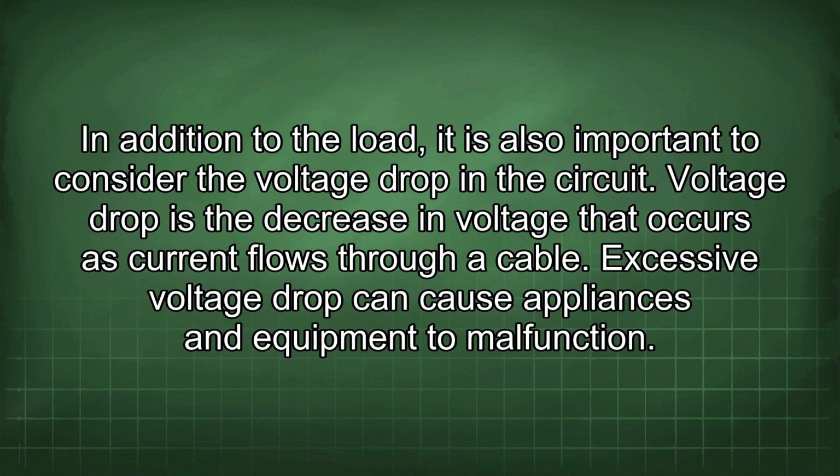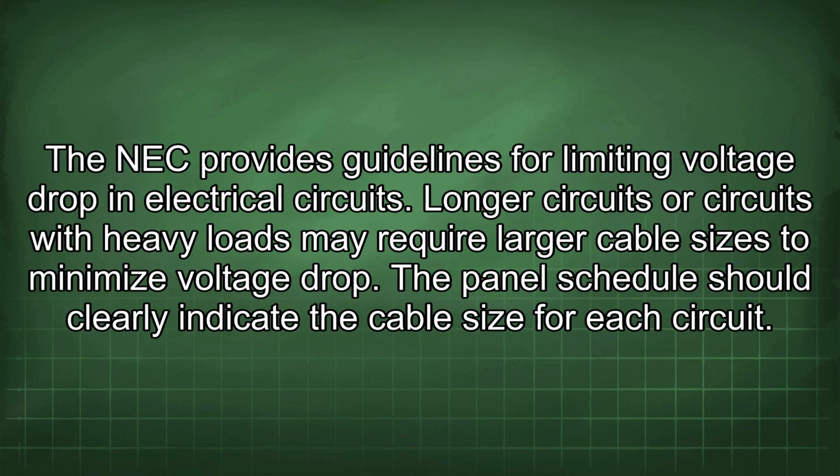In addition to the load, it is also important to consider the voltage drop in the circuit. Voltage drop is the decrease in voltage that occurs as current flows through a cable. Excessive voltage drop can cause appliances and equipment to malfunction. The NEC provides guidelines for limiting voltage drop in electrical circuits. Longer circuits or circuits with heavy loads may require larger cable sizes to minimize voltage drop.